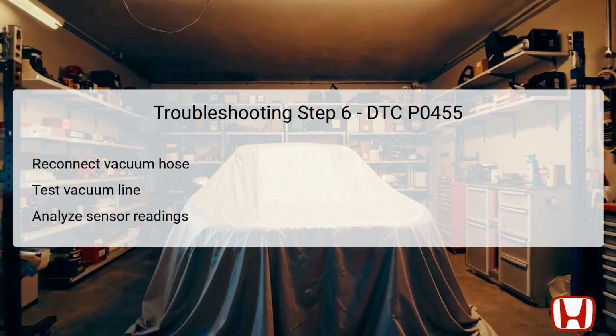Next, disconnect the vacuum hose from the EVAP canister side and connect the vacuum pump/gauge to the purge valve. Ensure the ignition switch is still in the ON (II) position. Repeat the vacuum testing process, applying vacuum until you reach the reading of 1.90 V on the FTP sensor. Monitor the sensor for any significant voltage change.